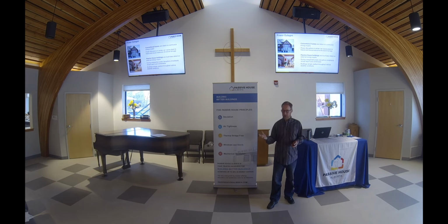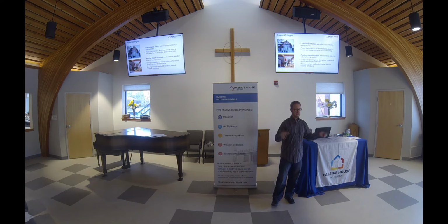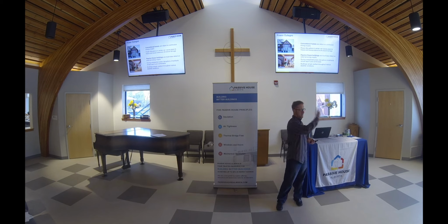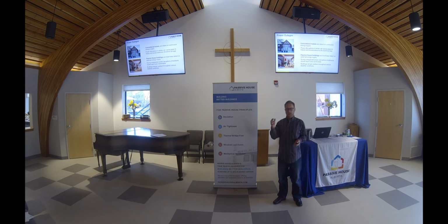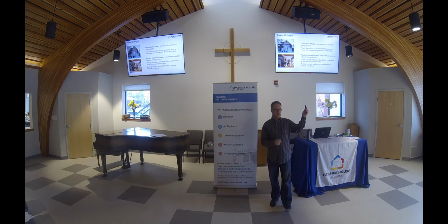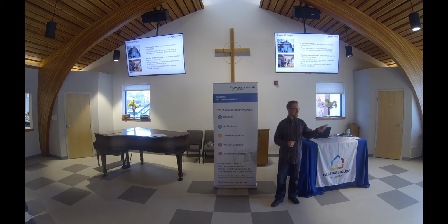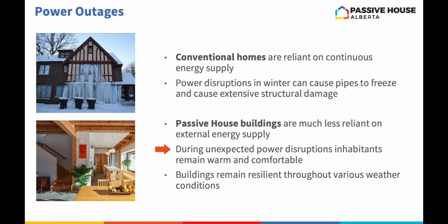And that's only if it's not cloudy. If the sun comes out at all during that time, your house will be fine. A passive house, if it's sunny, will not drop below zero, just because it's so well insulated. And if it sees the sun and allows the sun in correctly through the windows, the sun heats the house. You can get 30 to 60% of your heat annually in the heating season from your windows. Passive house windows do cost more. One of the reasons is they're also a furnace. They are a heat source for your house, at least the south ones. So you're less concerned about a grid failure, and that gives you building resilience and more safety.